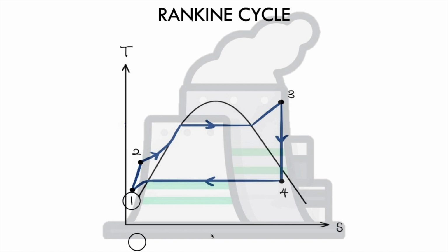From stage 1 to 2, water in the secondary cycle will enter a pump and be brought to a higher pressure. Then, from stage 2 to stage 3, compressed water enters the steam generator and turns into superheated vapor form. From stage 3 to 4, water in vapor form is brought to a lower pressure and temperature through a turbine, causing the water to turn into saturated mixture with quality close to 1. From stage 4 to 1, water enters the condenser and turns into compressed liquid.